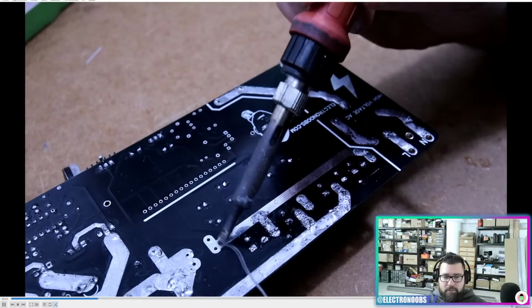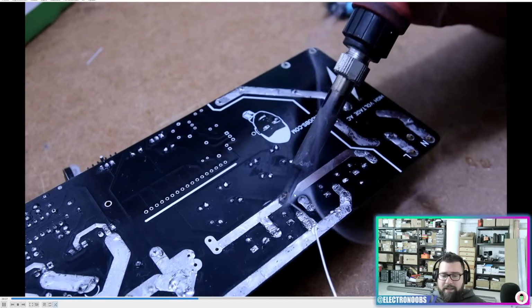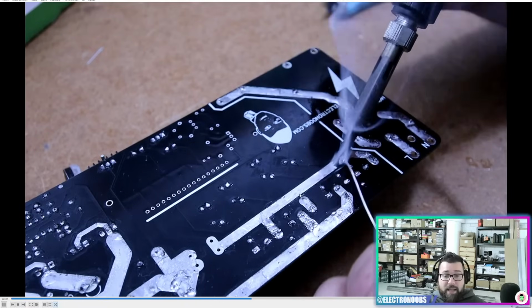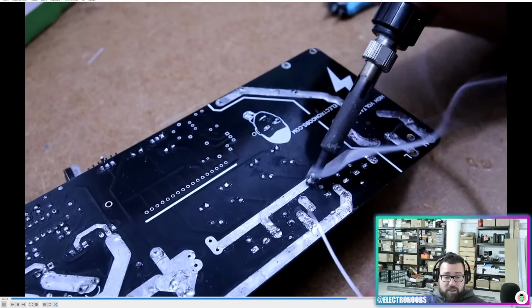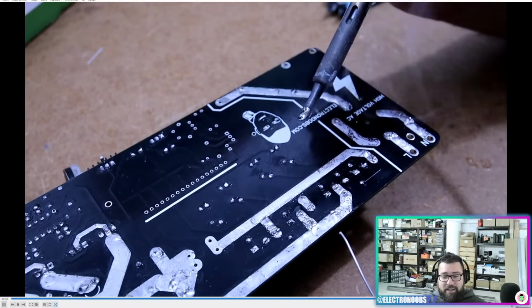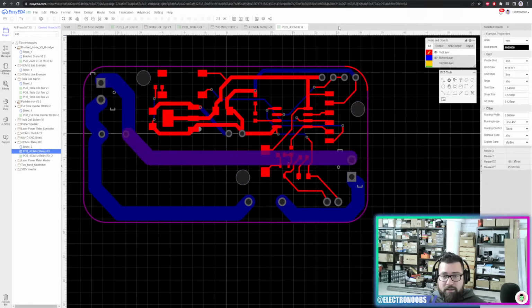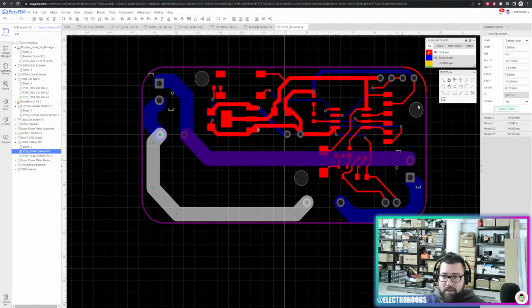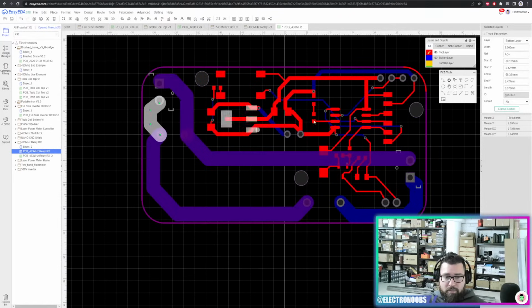And as you can see, just take that track and add a lot of solder, and like that, this track will be a lot thicker and it will stand a lot more current. And this is the cheapest way to do this. Just expose the copper and fill it with solder, and the more solder you add, the more current it will withstand. So anytime that you want to do that, just select the track that you want to make and click the expose copper.